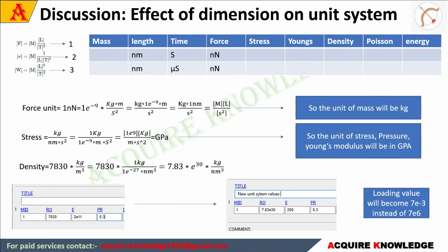Similarly, the loading that was initially 7 e to the power 6 Pascal, for this specific unit system that we are planning to work with, the value that we are going to enter into the simulation is going to become 7 e to the power minus 3.